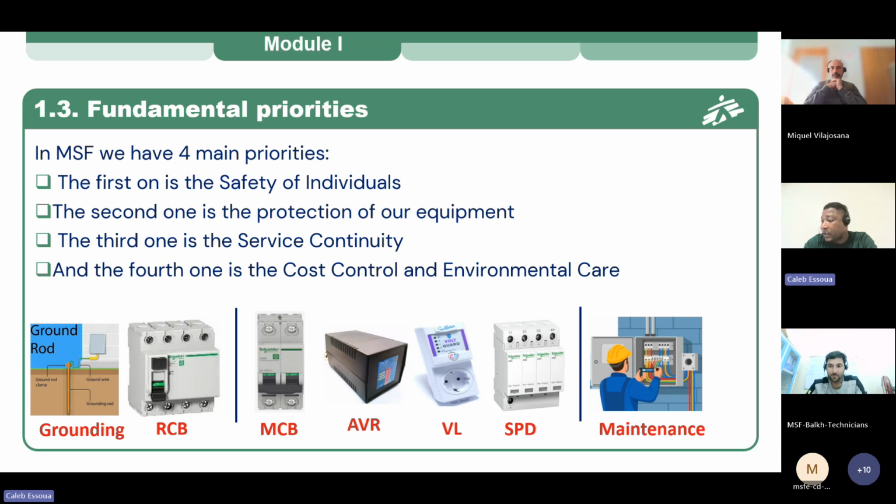Yeah, I think for a quick answer, basically your AVR, the voltage stabilizer, is having a problem, because normally it has to regulate the voltage in such a way that it is stable, and you cannot have this phase-to-phase value on the distribution box. If you are having this, it means your three-phase voltage stabilizer is having a problem.